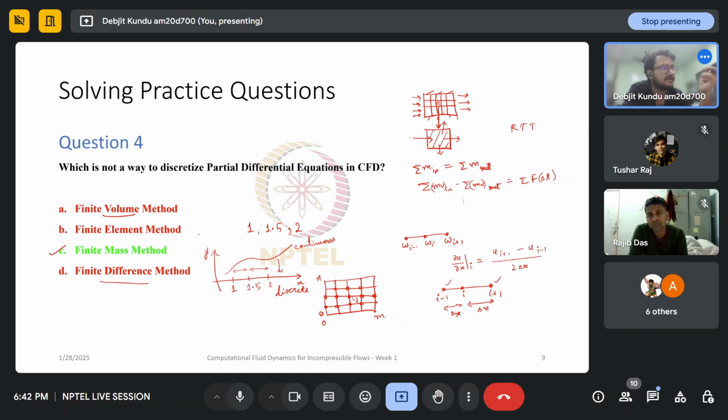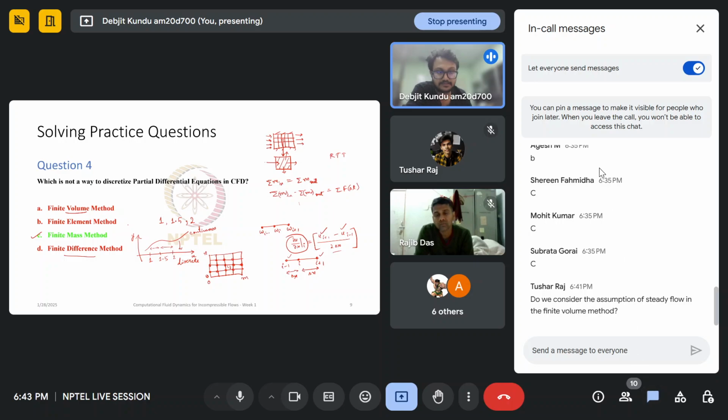So there are many ways. What I did over here is a central difference. We will learn these schemes. There are forward difference schemes, backward difference schemes, and so on. But the main funda is this, that I have a continuous function like a gradient, and I'm breaking that up into discrete numbers, like one number minus another number divided by something. That's what finite difference is. I hope that gives you a broad overview of the techniques. We will discuss in detail later.